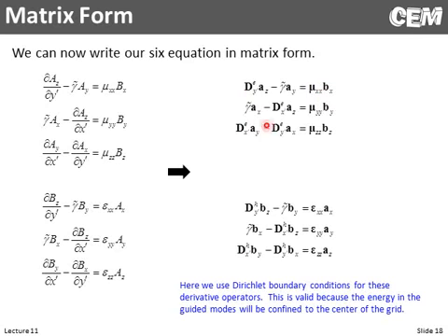So we jump immediately. We actually don't have to touch any finite differences. They're hiding behind the curtain, if you will. We're going to write this function that calculates those banded matrices. So you just tell it the size of the grid and the resolution. It calculates those matrices. It's very easy to diagonalize your materials arrays, and so we can immediately build those equations.